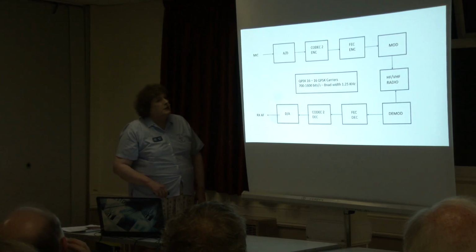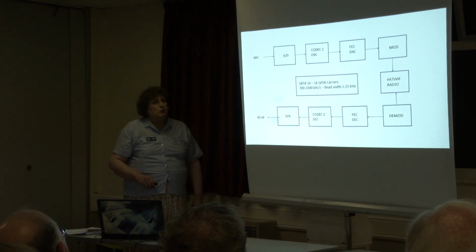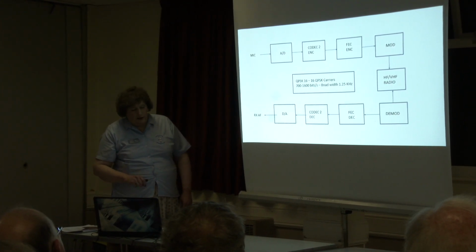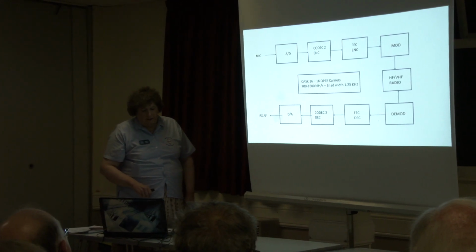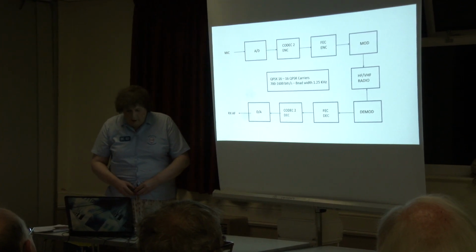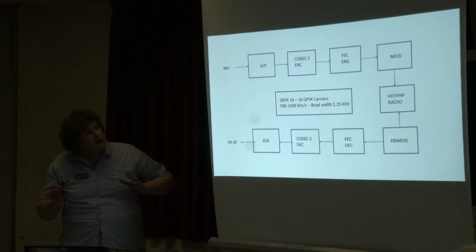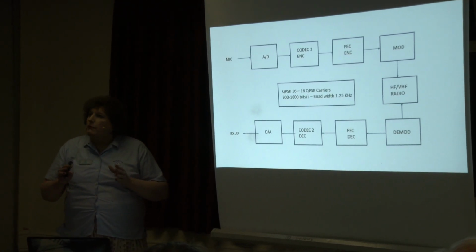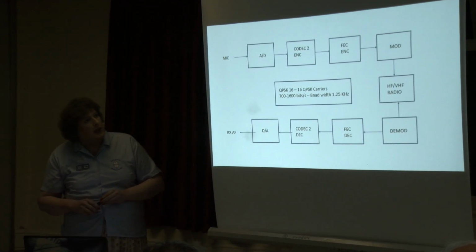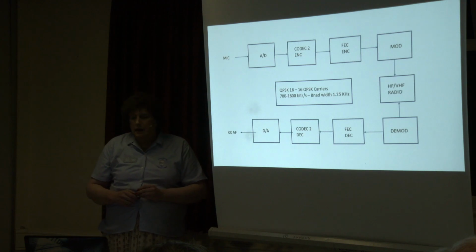When we go down to 700 baud, and I'll come to why we use 700 baud in a minute, we have 650 bits per second for voice encoding, 50 bits, no forward error correction because it's not needed at the lower data rate, and there's 14 75 baud QPSK carriers. One of the things it also has on the lower bit rate is frequency diversity, which is used to combat fading and slight drift on some radios, so it can resynchronize itself and keep itself in lock.